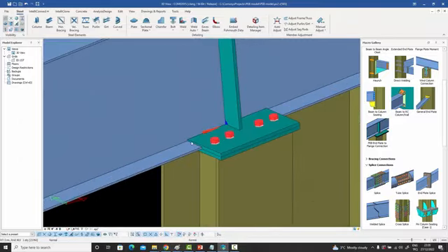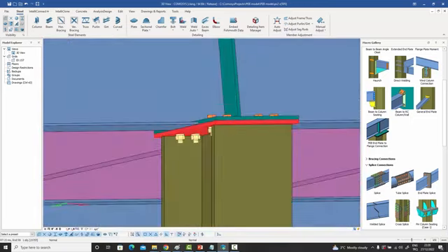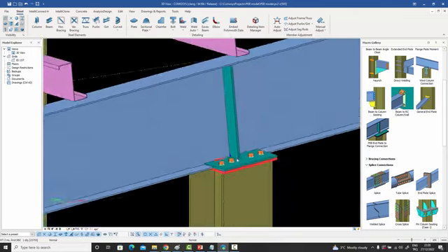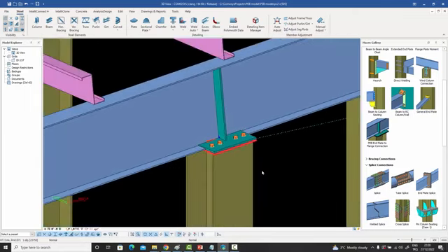The bottom flange is cut out and this plate replaces it because widening is needed at times. And another end plate is given at the end of the column. You can have complete control over where the bolts are and whether the stiffener will be created or not. It is a very convenient connection, allows you to connect the column to the bottom side of the beam when the column is facing in this strong direction.